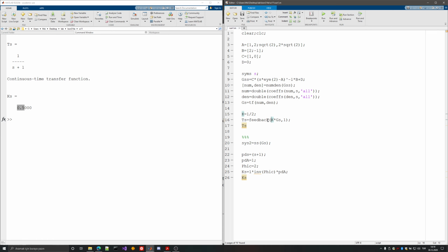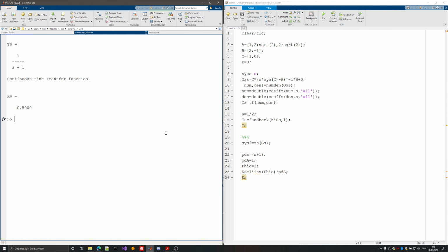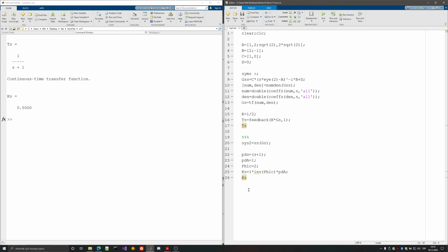So if you have a first order system, then you're basically feeding back the output. But keep in mind that the Ackermann formula needs to have a minus, because it told us that u is equal to -kx. So there's also a minus sign. And keep in mind that this equivalence is based on 0 reference. So you should use 0 as the reference. Then your error becomes minus y, which is minus cx. So here we have k, and they will be the same.